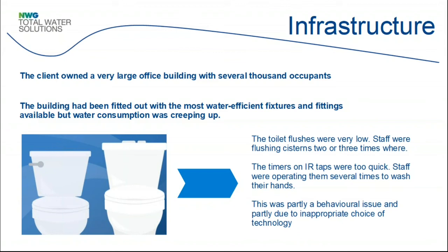And one of the recommendations for the audit was that by maybe doing a bit of behavioural work with the people, doing this rolling programme of changing the system mechanisms and the flushes and things like that, would probably help to nudge down the water efficiency a little bit. So you might be able to get down to maybe 35, 36 litres per person per day. But that was actually very good. And the amount of effort it was going to take to get down any lower than that probably wasn't justified by the benefits it would bring.